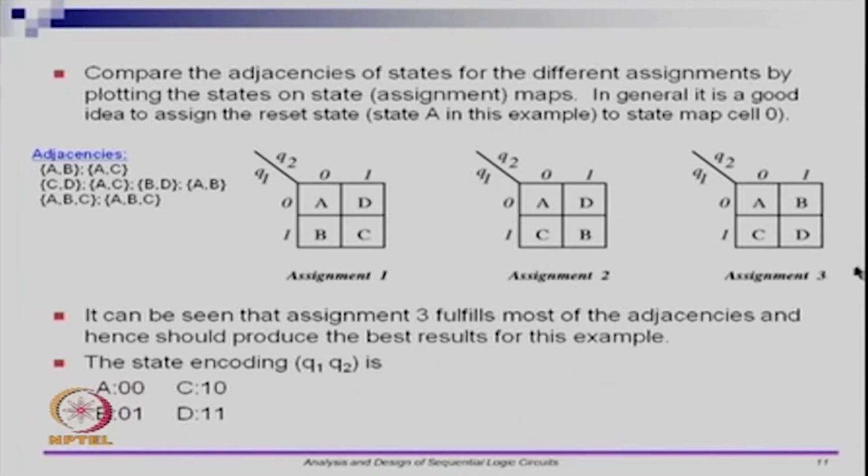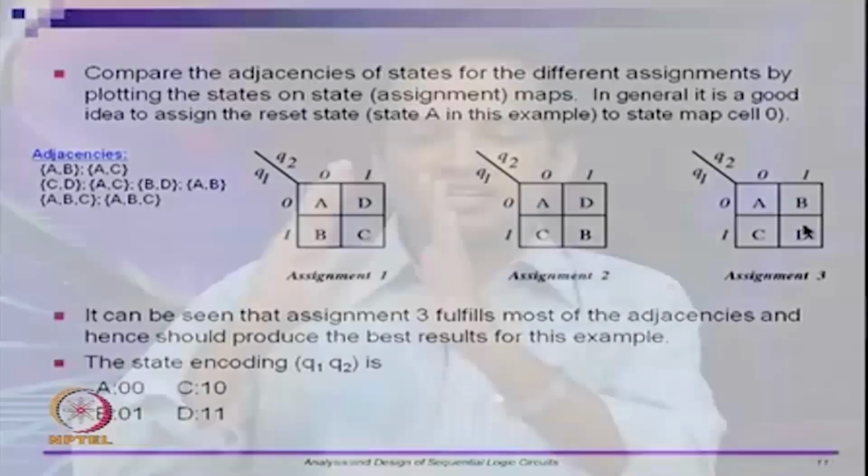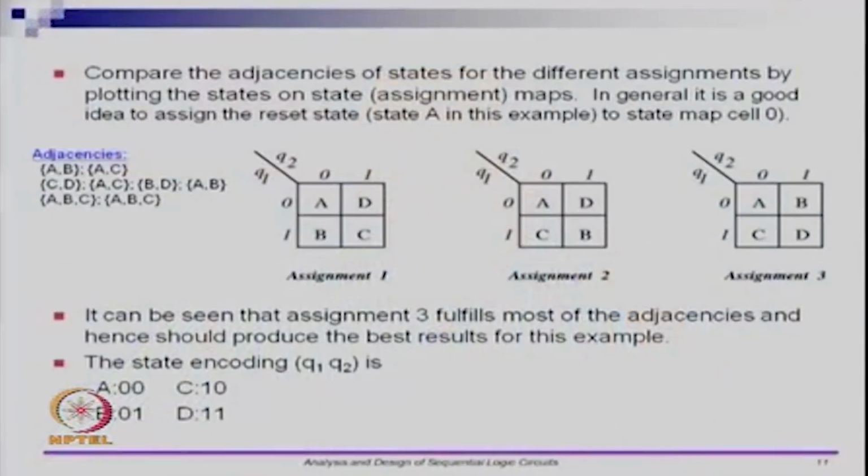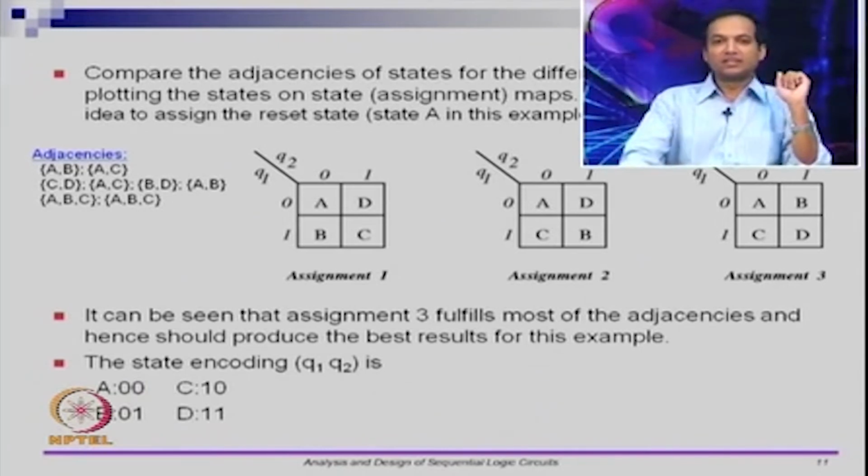The reason why we want them to be neighbors of each other is that if they are neighbors, later when you derive the next state and so on, you will be using these bit positions, ones and zeros, and they will become close to each other. If you look at the next state logic or the output logic, these are combinational circuits. In these combinational circuits, states which are close to each other in the table shown here will put ones in the truth tables when you do the combinational minimization. That is the reason why we want to follow this heuristic.